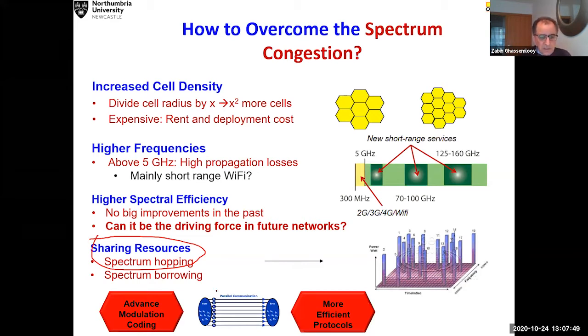And of course, on top of that, you have the signal processing, which caters for modulation scheme and coding, especially the modulation scheme based on multi-level, stacking them up as much as possible, or using many carriers, bringing the carriers as close as possible to one another, watching out for the inter-carrier interference and so on.